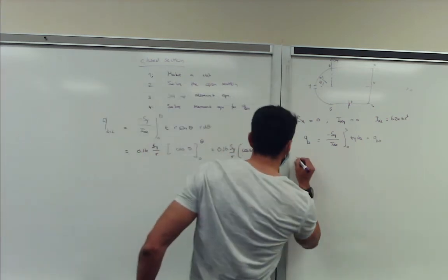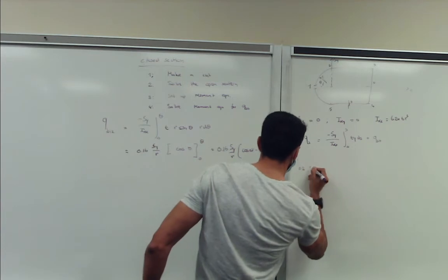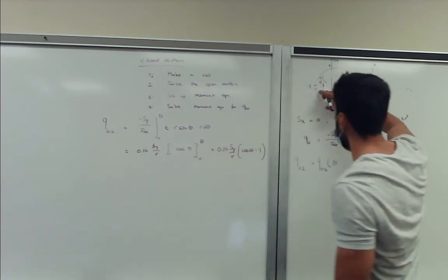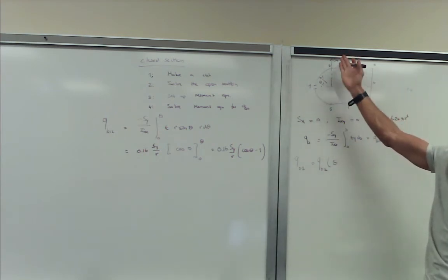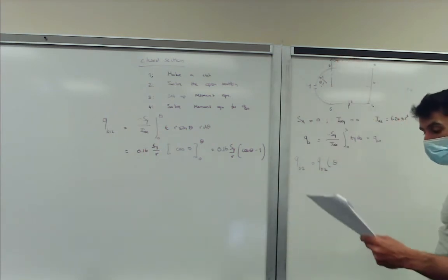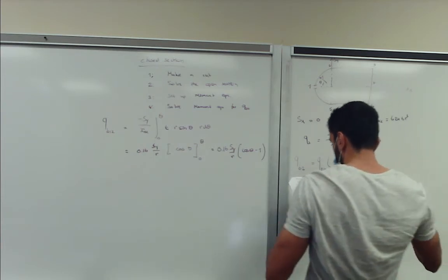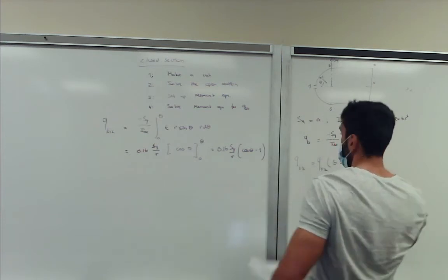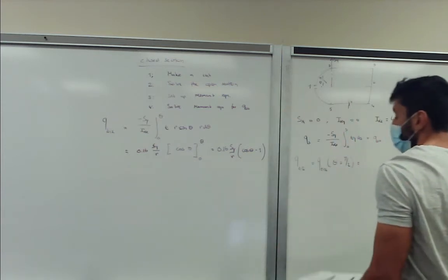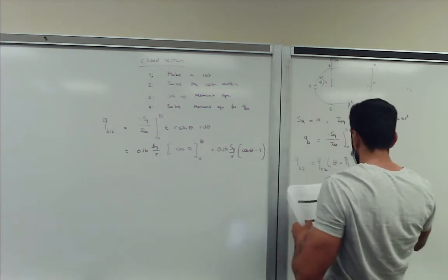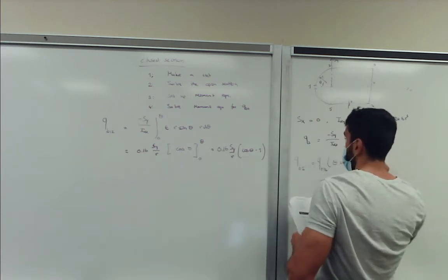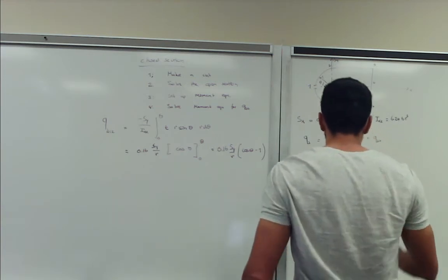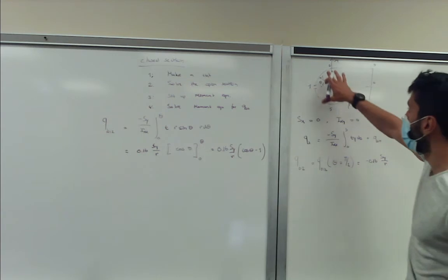So if we evaluate QB at point 2, it's equal to QB12, and theta, in this case, equals 90 degrees, which equals pi over 2. So you plug this into this equation, and because cos of pi over 2 becomes 0, you get minus 0.16 Sy over R. So that's our shear flow value at point 2.